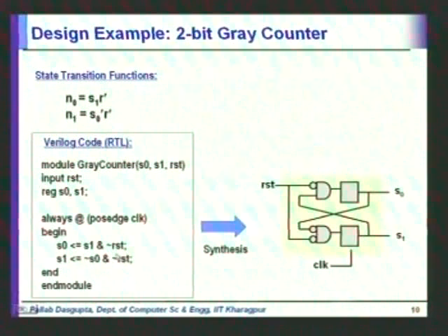So the design is entered at this level and is output by the CAD tools at the circuit level. So it can produce it at the gate level, at the transistor level, and finally when you have completely laid it out, it is going to produce what is called the GDS2 format, which then goes directly into the fabrication system.